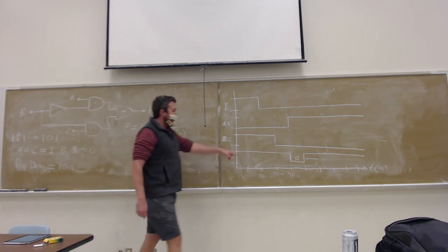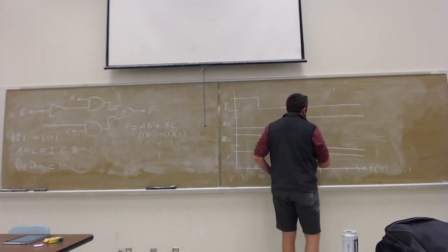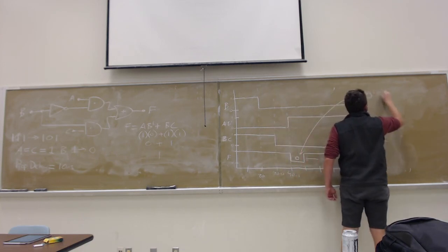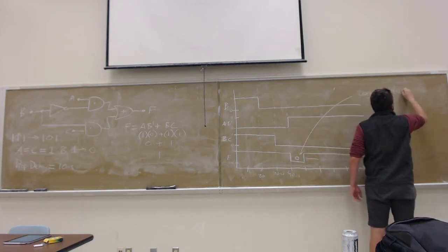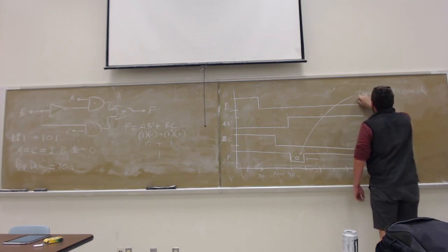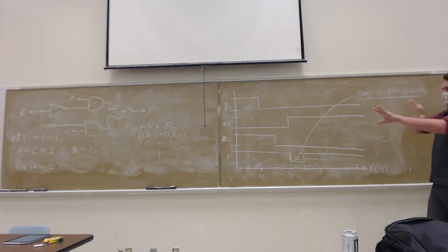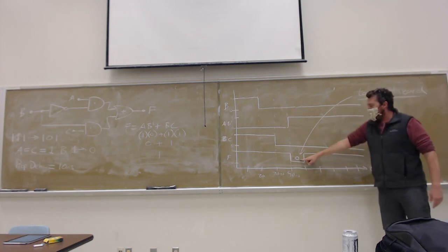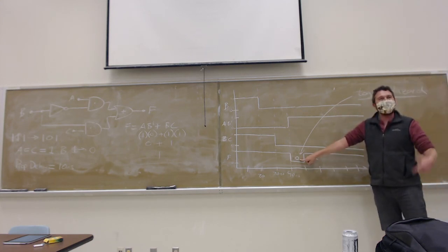So this thing happening right here is called a logic hazard. A logic hazard is when, due to the topology of the circuit and the interaction between the delays, an unexpected or an unwanted change in the signal occurs.